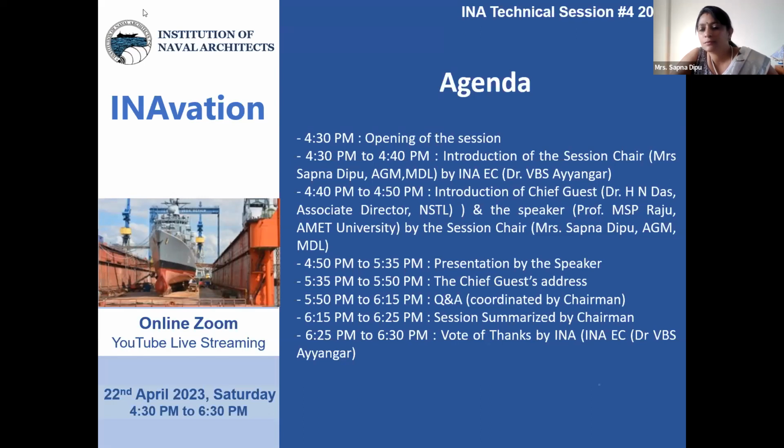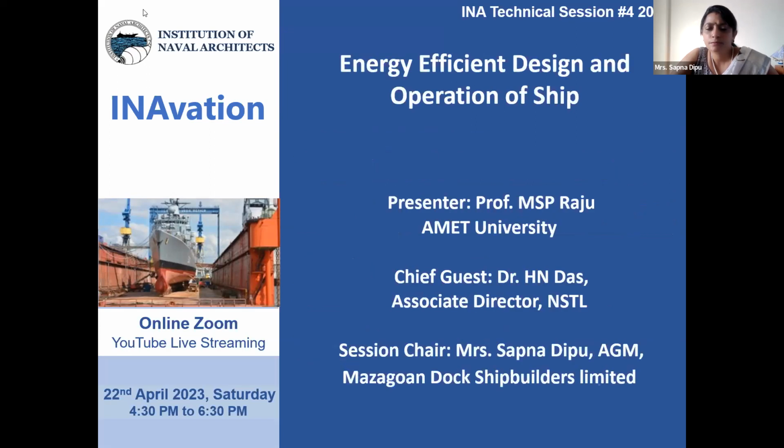It is a pleasure to join this kind of seminar. I am attending in my personal capacity. When we had a changeover from single hull tankers to double hull tankers, some vessels could convert from single hull to double hull. And there was a window period given for some years, depending on the date of construction, date of keel laying in MARPOL, and then the vessels were phased out.